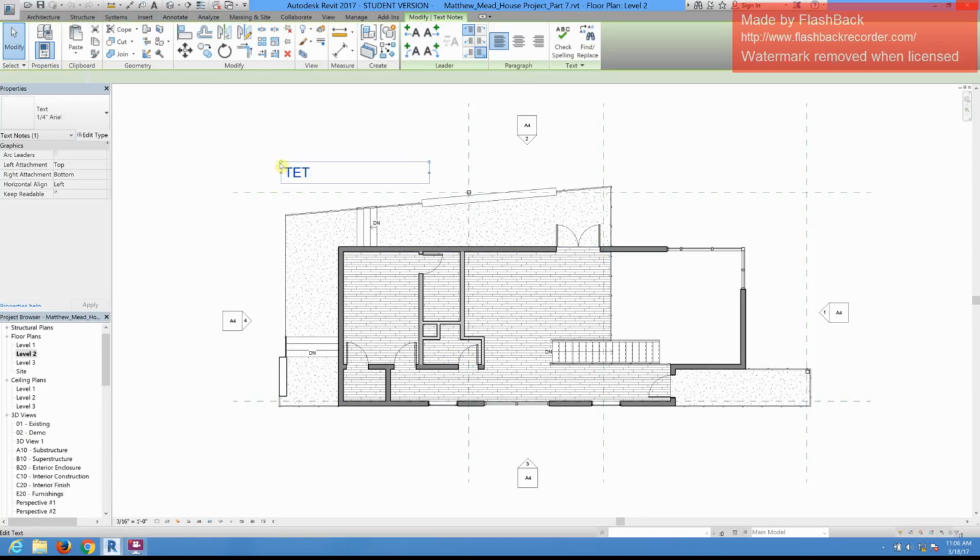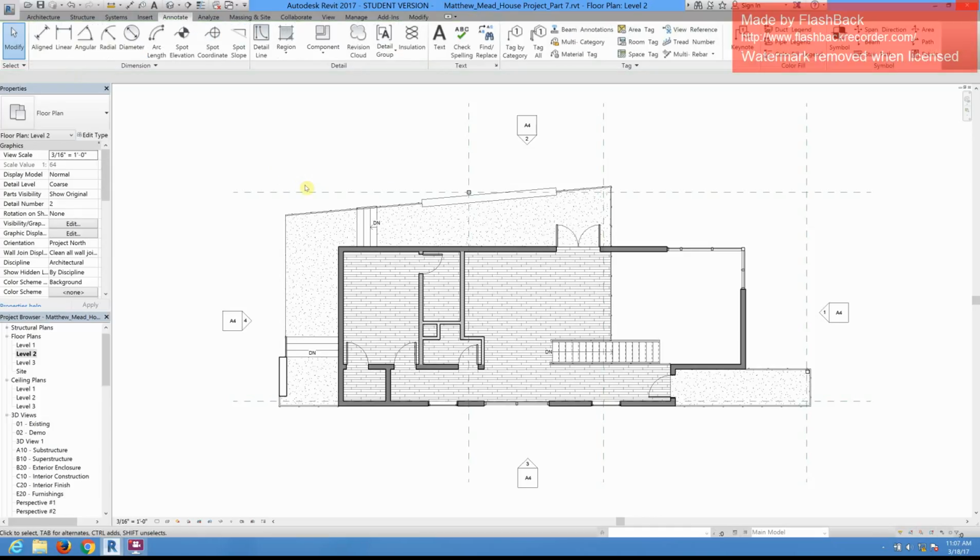And let's talk about creating view templates. So I know a lot of you have probably realized, as you're creating views, that there are aspects of that view that you don't necessarily want to plot. So you might go through the process of going to your visibility graphics and make some changes to that view. Okay, so for example, let's find...